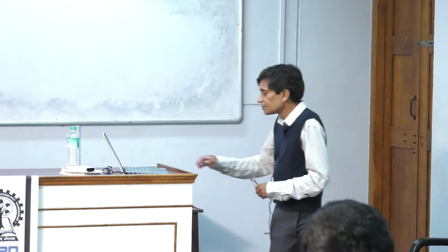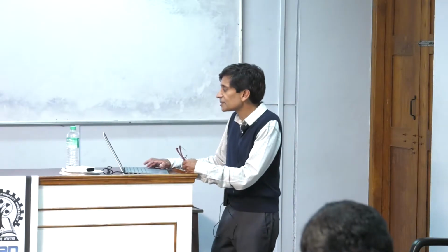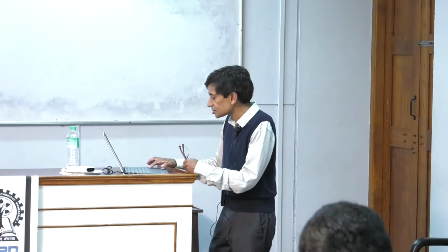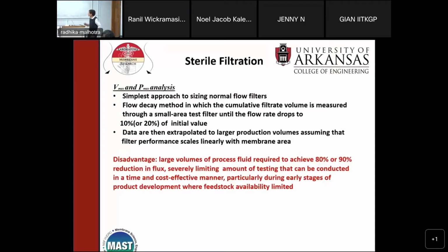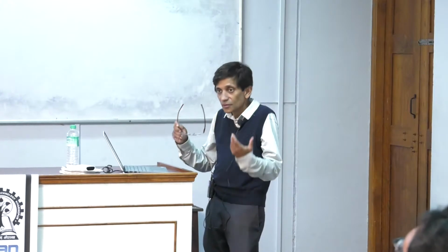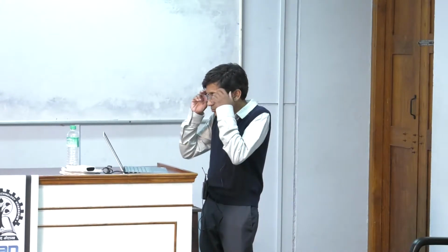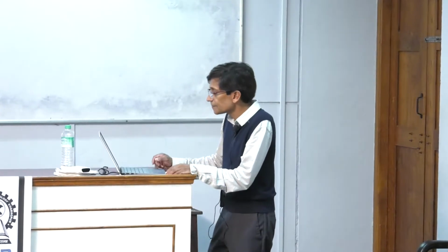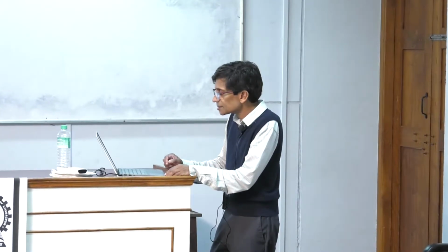And if you remember, just before we took our break, we were talking about the fact we need interconnected pores and so forth. So typically, this is what is done in industry. We talk about a Vmax and a Pmax analysis. So maximum volume that you can process and maximum pressure. And it's the simplest approach to sizing normal flow filters. So basically these sterilizing grade filters.